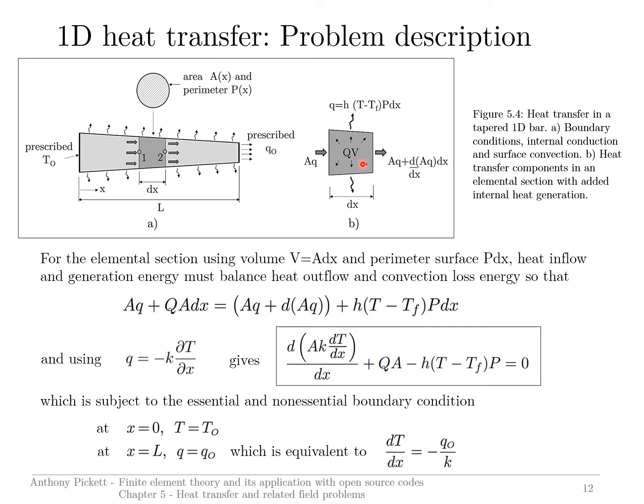I'm not going to consider in this particular case this mass effect, time-dependent mass effect due to density of the material and capacitance of the material. So this is the same as the Poisson's problem in effect, because we do have internal heat generation being considered. But the derivation here would also apply to the Fourier problem if we just neglected this internal heat component.